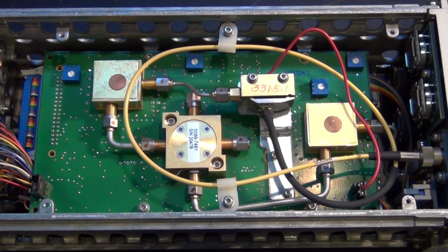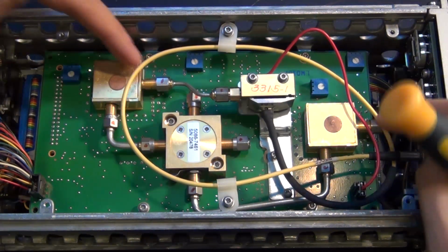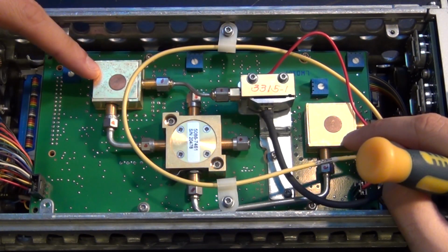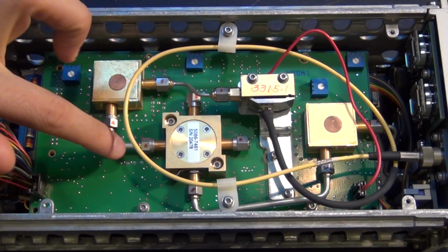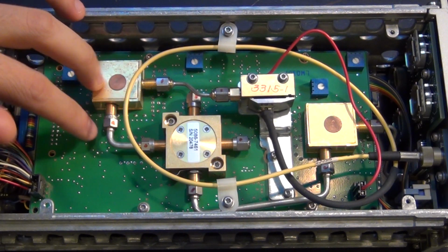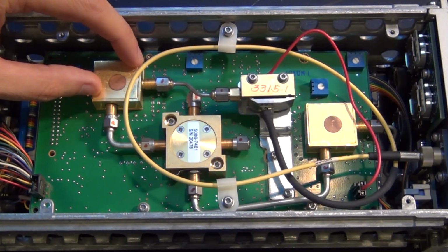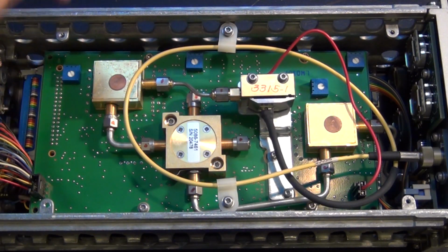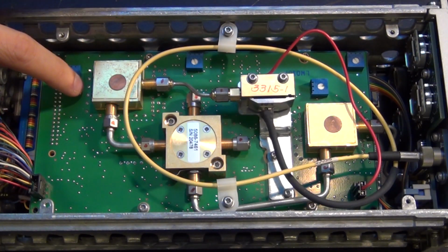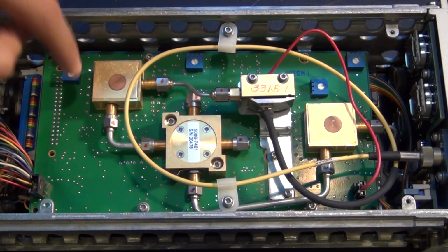This is our full bandwidth 50 gigahertz repetitive signal that we are trying to subsample and digitize, which means that these guys are our samplers. Very high frequency input, and the output is going to be the IF low frequency, and this input here is not the output of the sampler, this is the clock of the sampler. This is the impulse train that comes into the sampler in order to do the down conversion into the IF frequency and then ultimately going to the ADC, which means that the IF coming out is actually into the board, and once we flip it over, we should be able to discover it on the other side going into the board. So we have our impulse train coming in, analog input coming in, IF going into the board.